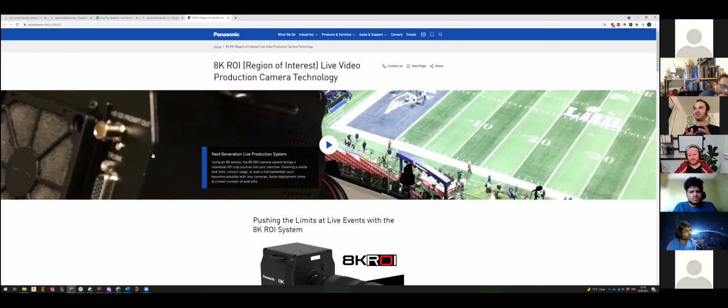If you're trying to bin a sensor, are we all familiar with the notion of binning? I know what it means for just any data. For a camera sensor, binning is just grouping up blocks of pixels. If I have a 4x4 camera, a very small camera, and I'm running it at no binning, 1x binning, I get the full 4x4. If I do 2x binning, I get a 2x2, and if it's 4x, I get a single pixel. In a lot of sensors, that allows you to average the signal together, because the noise is distributed across the sensor. So you get a lower noise estimate of the signal.